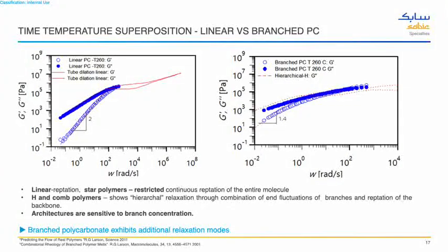Now, the same concept here. Now I talked about branching, hyperbranching. Now I talk about branched PC also to see how it behaves in terms of the rheology. G prime is the elastic component. G double prime is the loss component. You can see it with the angular frequency. In a classic test in the literature, it goes to the slope of 2. It's the elastic component.